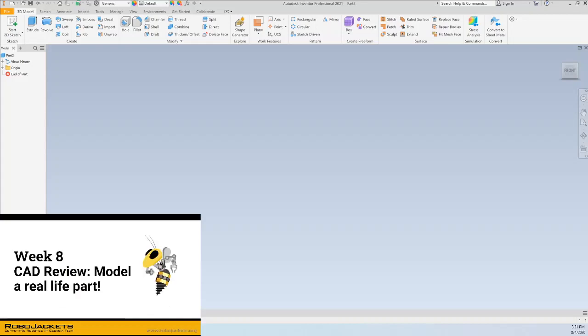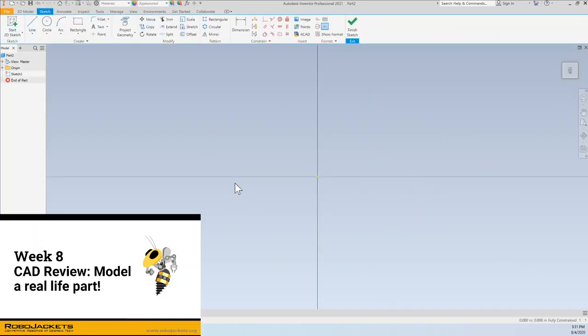So with that in mind, we're going to get started. Now the object that I've chosen is a small measuring cup. And I've already made a small model of it before, so this shouldn't be too long for me measuring things. But I'm going to start with a loft, because it's not a simple extrusion straight up. So it's got a straight side that goes into a circle on the base.